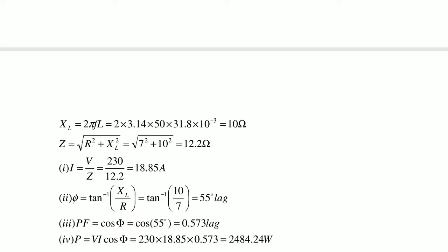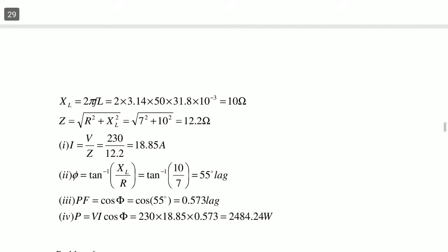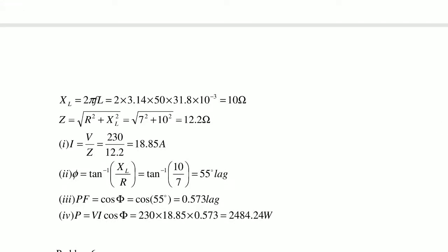Now the power factor is cos phi. We determined phi is 55 degrees, so cos 55 is 0.573 lagging power factor.